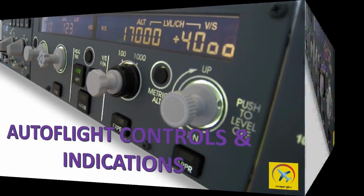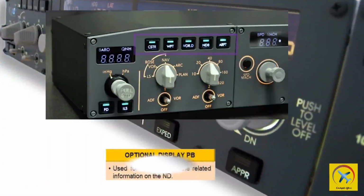The data display buttons display optional data, constraints, waypoints, VOR, non-directional beacons, and airports. When the airport button is selected on, the airport symbols are displayed as a magenta color. The airport symbol is displayed white when the runway is not specified.